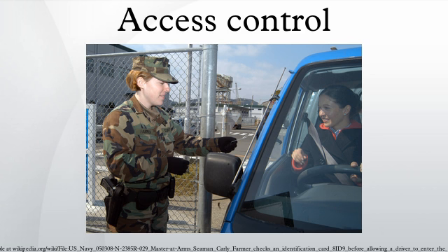If there is a match between the credential and the access control list, the control panel operates a relay that in turn unlocks the door. The control panel also ignores a door open signal to prevent an alarm. Often the reader provides feedback, such as a flashing red LED for an access denied and a flashing green LED for an access granted. The above description illustrates a single-factor transaction.